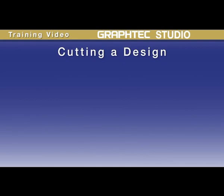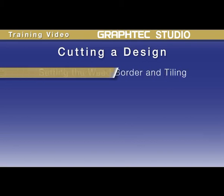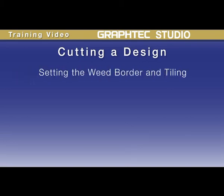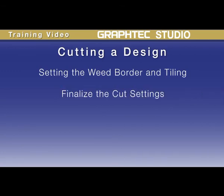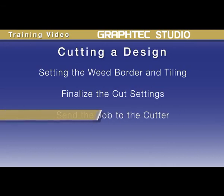Let's review the steps and settings for cutting a design. The first couple of steps are configuring options such as the weed border and tiling. After these are configured, the next step is to click on the Cutter's tool icon in the side panel. This is where the final cutter settings can be adjusted, such as the cutting condition for the intended cutter and material. The final step sends the job to the cutter.